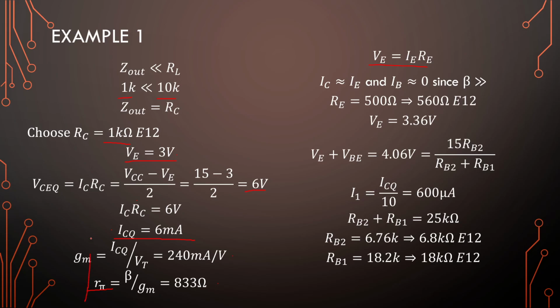So you can approach this in that direction for a specific input impedance. Okay, so since it's design, you always need to pick a point and work from there on. If a specified input impedance for this particular amplifier was given, I would have started with R pi and worked backwards, towards something that satisfies this specification right here.